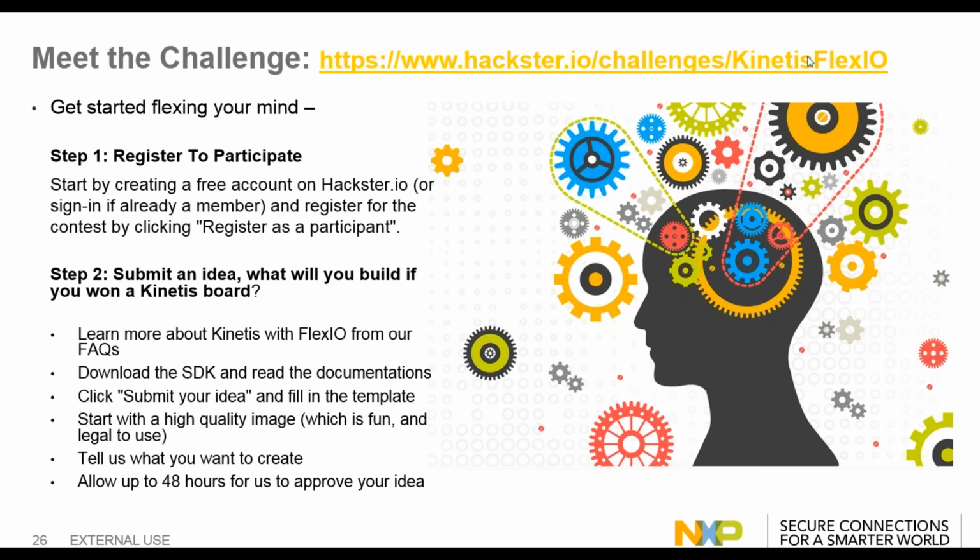So for the case of reconfiguring clocking, what would probably be more feasible or easier to implement, instead of trying to change on the fly the clocking associated with a certain FlexIO function, is to have incremental shifters and timers to do that function. In that way, you use certain shifters and timers for function 1 and different shifters and timers for function 2 that operates at different clocking.